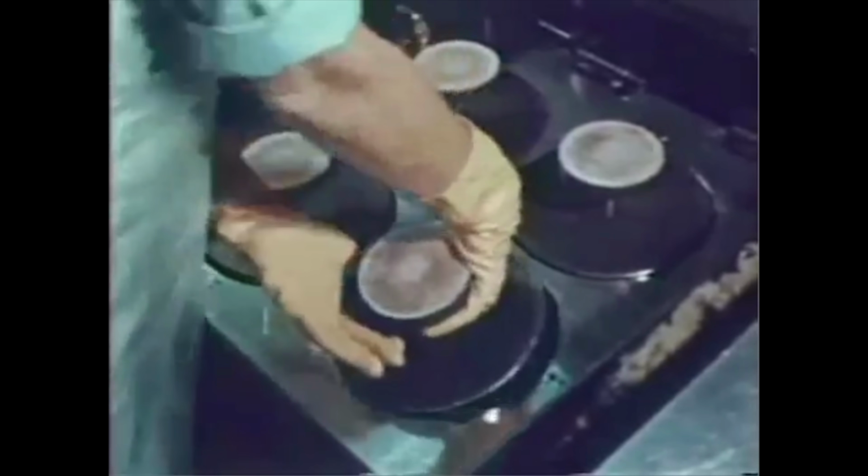After cutting, the wafers are very carefully polished, so you end up with a mirror-like surface, which is essential in the preparation of the integrated circuits. The finished chip is about 5 thousandths of an inch thick. Let's take a look inside the silicon. This is a cross-section of the wafer we've just watched being made. To protect it from the outside world, we allow oxygen to react with the top surface and grow an oxide called the passivating silicon dioxide layer.